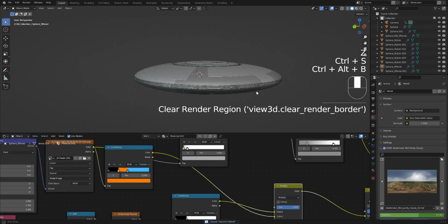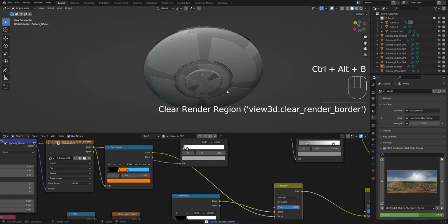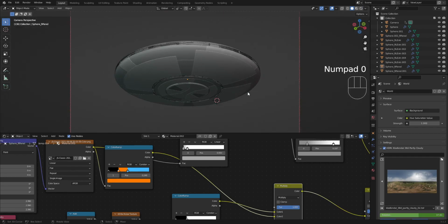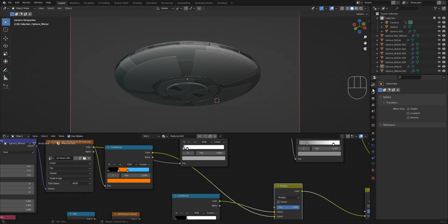Okay, and going to snap the 3D cursor on this side. So snapping the 3D cursor, go to the active tool and workspace settings in the properties window, and then workspace.